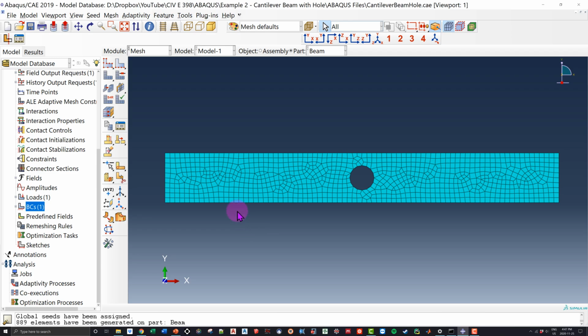Now, this isn't the only option. Again, this right here applies that approximation to every surface within this model, or every edge. But if I want to, I can define each surface separately. So instead of seed part, I can go to seed edges, and I say, all right, well, this edge right here, you know what, 25 is a little bit too small. So let me select the two vertical edges. I can click OK.